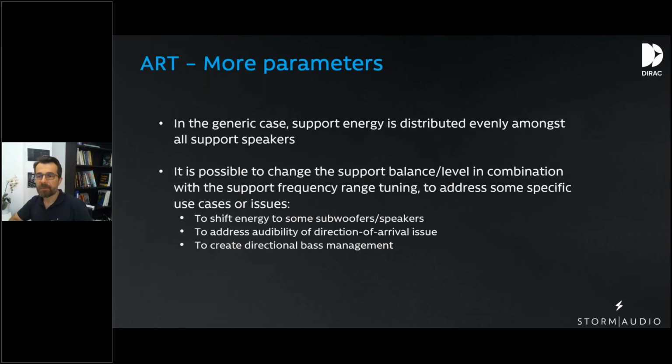Okay. Now there are use cases where you need to do more, and this is where you might need to change the support balance, the support level, in combination with the support frequency range. Usually this is because you want to have a different energy spread in the room. So in some use cases, you may be looking for more energy in your front wall versus the back wall for your subwoofer. So that's one use case.